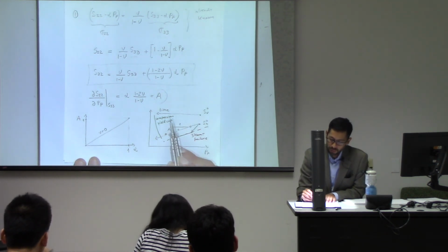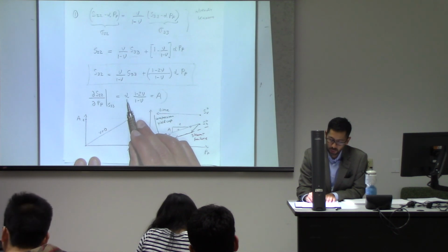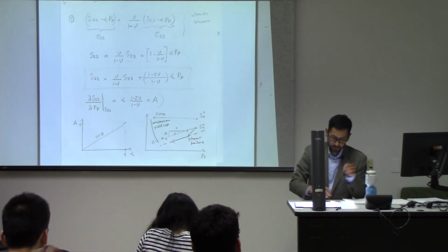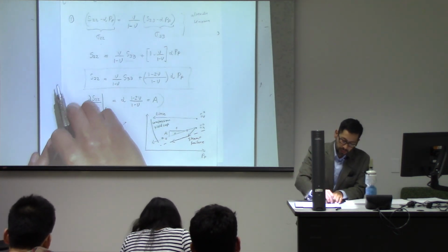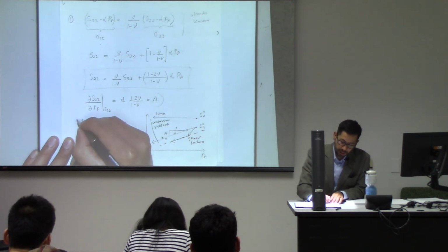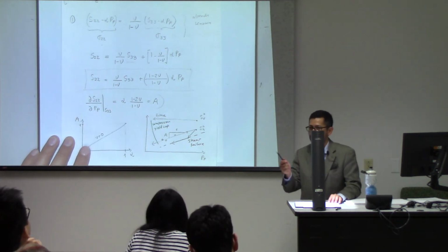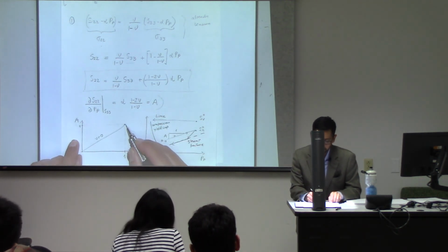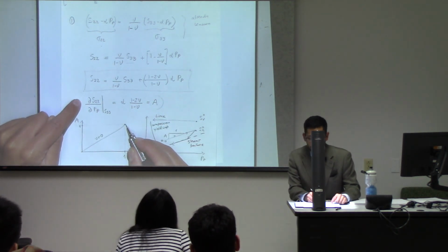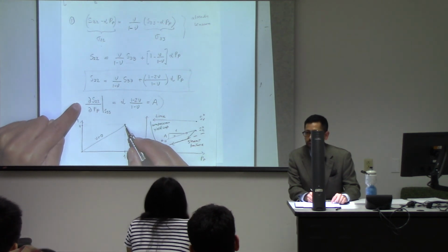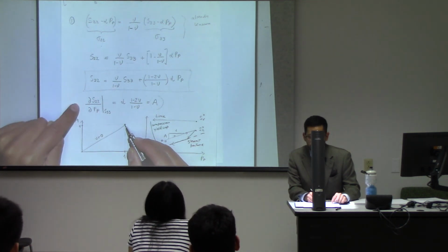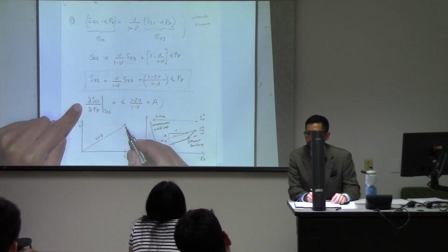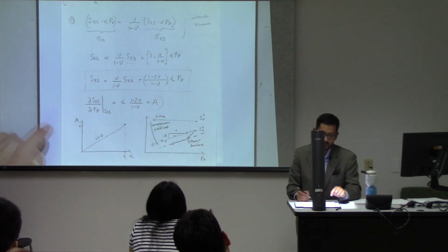So this is equal to 1, but wait. Let me rephrase what I said, because I didn't see that you were happy. If this one is equal to 1, the change in total stress is going to be equal to the change in pore pressure. But there is not going to be a change in effective horizontal stress. Effective horizontal stress is going to remain the same. Okay.